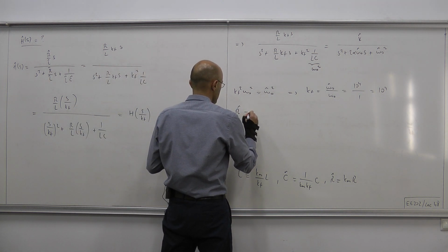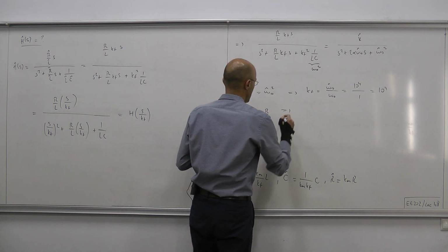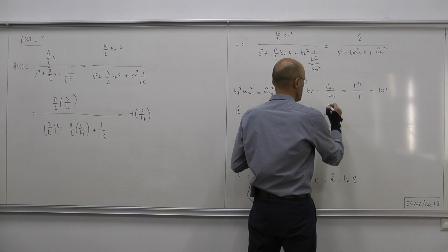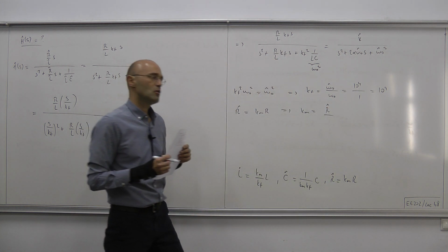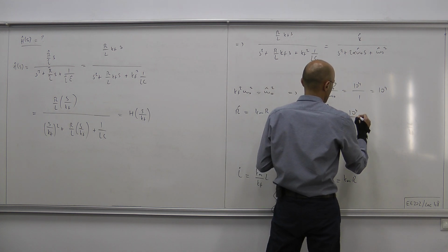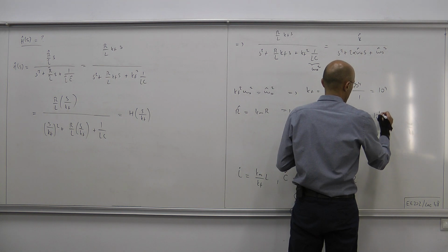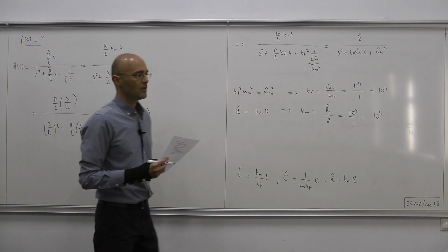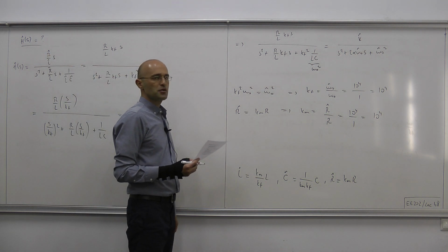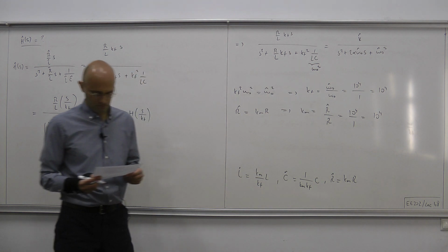Also R hat equals km times R, therefore km should equal the desired new resistance value over the initial resistance value R, which is 10,000 ohms over 1 ohm, which produces the magnitude scaling factor equals again 10,000. Okay, so